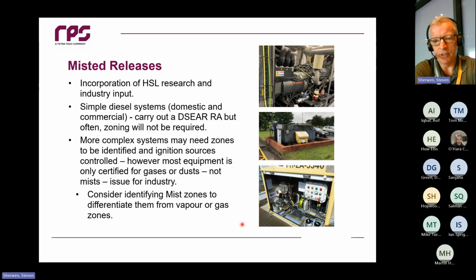But 99% of the diesel installations in the UK, and almost anywhere in the world, aren't high pressure complex systems. They're gravity fed systems, road tanker loading, filling up vehicles, emergency generators, fire water pumps. EI15 still says that a DSEAR risk assessment is required around those installations because diesel comes under the remit of DSEAR. However, for a lot of those installations, where you're at low pressure with commercial, well-maintained proprietary systems, zoning shouldn't be required.